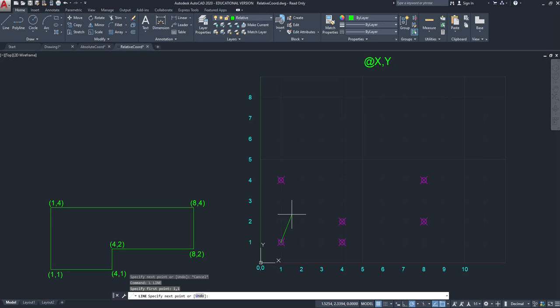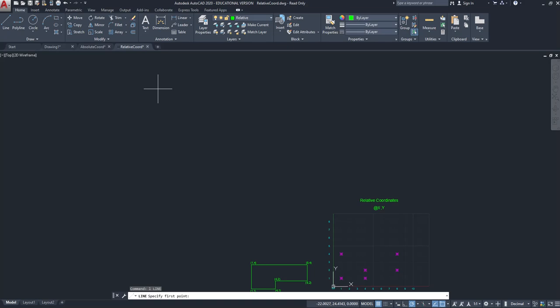I don't think, I'm going to start at 0, 0, and I'm going to draw to 1, 1, unless I'm doing something that needs that. I just start drawing, okay? So the point of this relative input is that I don't always know where my stuff is in AutoCAD, but I know different lengths or dimensions I need to generate, okay? So if I'm out here in space and I click, I don't really know where I'm at, per se.